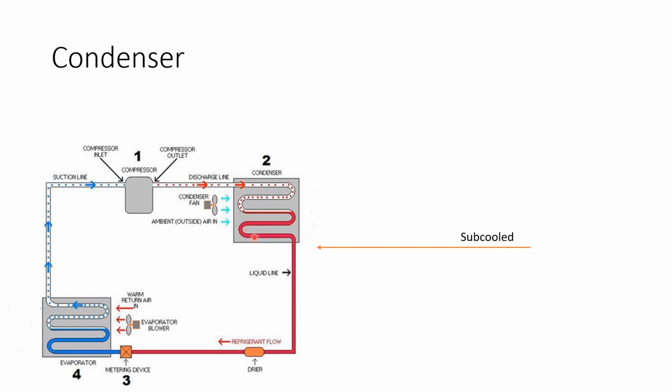And when we come out of the condenser, we keep rejecting heat throughout this whole second part of the condenser, and it becomes subcooled. So this is a subcooled liquid. Now, if anybody's ever touched or measured that liquid line coming out of the condenser, you will know that that is extremely hot. It's a very high temperature. You'll burn yourself. You'll regret that you touched that line set. So you're thinking the term subcooled doesn't make much sense.